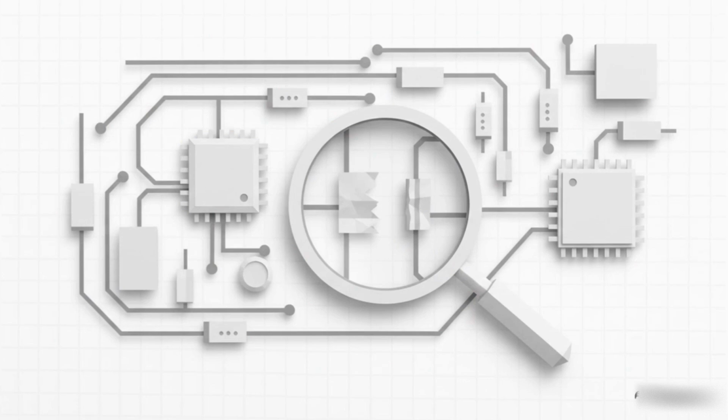And this is why this is such a powerful technique. That power balance check is like a built-in diagnostic tool. It confirms your whole analysis is correct. If you get 0, you know you're good. If you get something else, it tells you a mistake was made. Maybe you flipped a sign somewhere, and it tells you that you need to go find it.